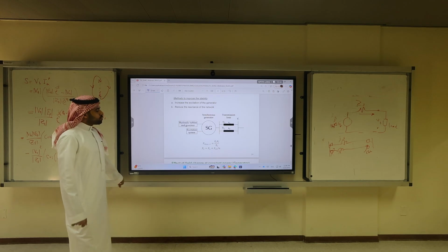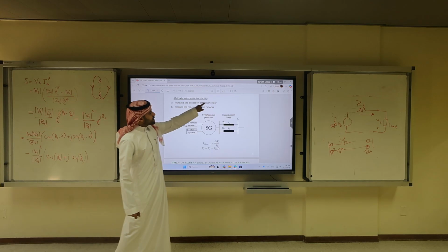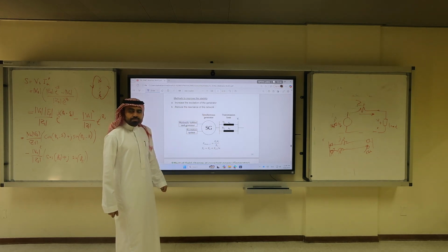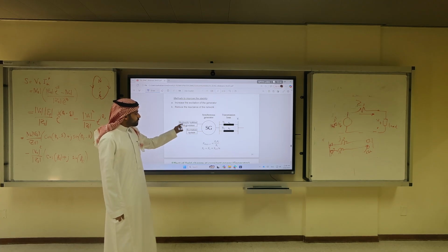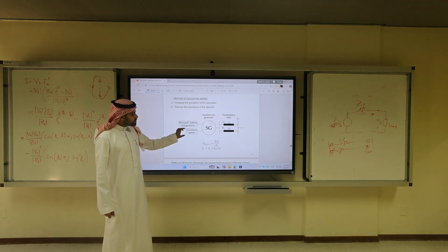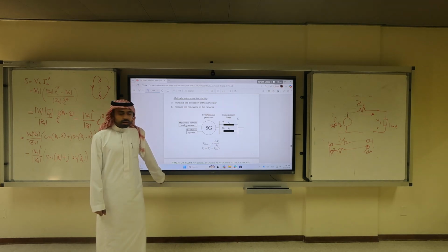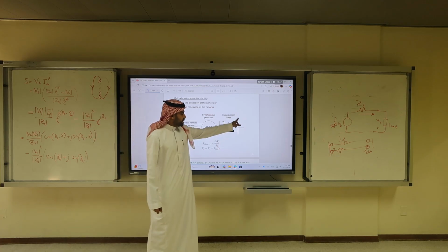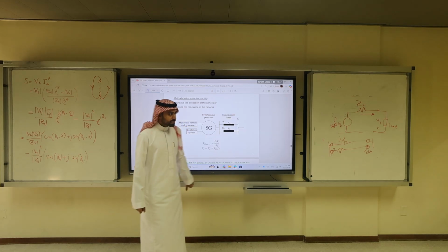That's what I told you. What are the methods to improve the stability? 2 methods. Increase the excitation of the generator, reduce the reactance of the grid, the network. So in the excitation, so this is the hydraulic turbine and governor. This is the excitation system. If I increase the excitation system, I increase EF. Remember, V terminal is fixed. This is R means receiving end. This is sending end. This is receiving end.